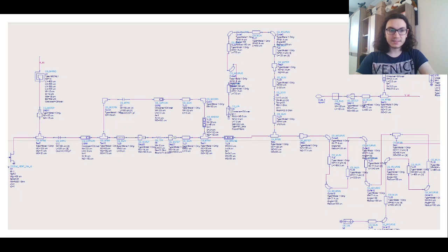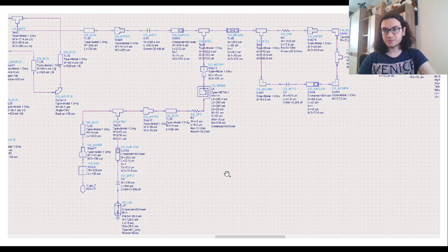And this is the output matching network of the LNA and the input matching network of the second stage with the stability networks. For parallel elements, I designed a square-like design in here, and it is the continuation of the input matching network of the second stage. As you can see, the transmission lines and the bending component steps here. Also, I used bridges for combining two T elements.